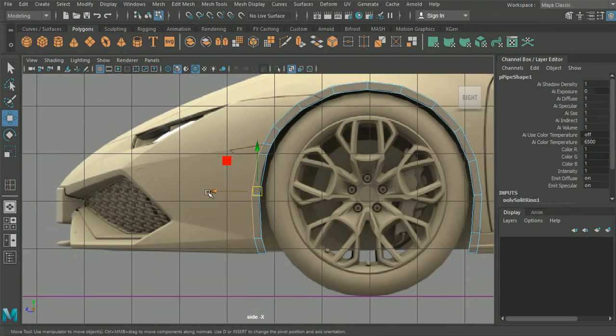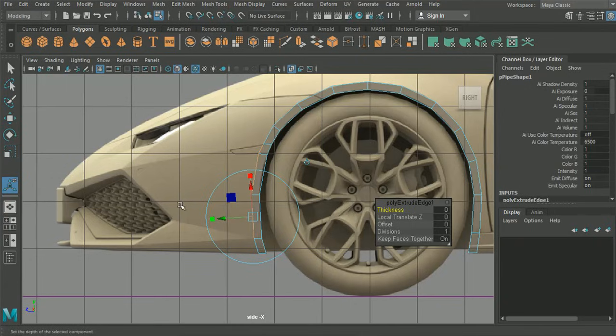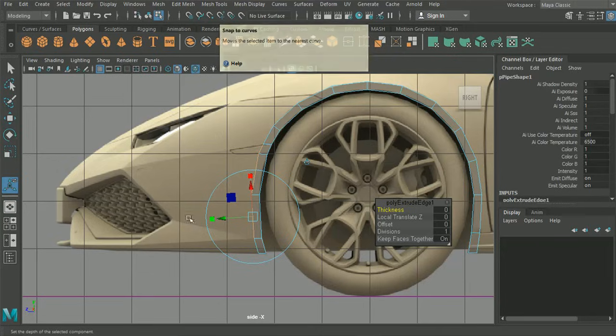So what we're essentially going to want to do is extrude out so that we have a line at the edge of this signal here which runs down. We're going to want to have a line halfway through here just to give us some extra polygons to work with, and then a line that runs all the way down this edge here. Now, the way that I like to do it is I like to take the extrusion in one go. So we can hit Control E, which is going to bring up this option, or we can simply hit the extrude button here, or we can head into the mesh tools for that as well.